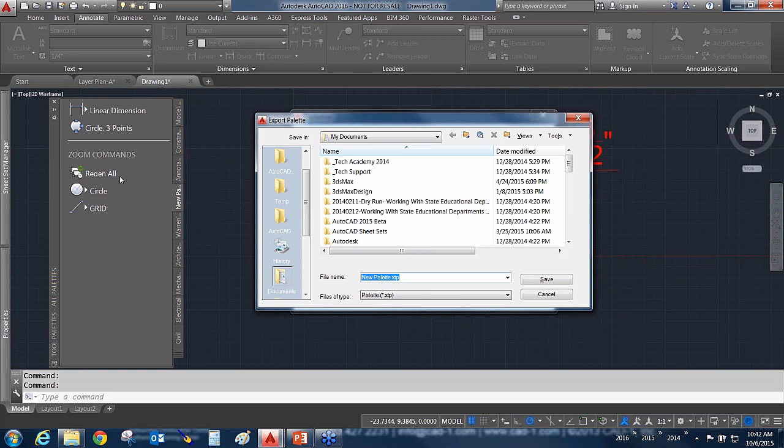So before you drag and drop a block, you've got to make sure that what we call the library file, where that block is coming from, is sitting up on a shared server, shared resource somewhere. Then you drag and drop it so that it's going to hold that particular location. Then you can go ahead and share your tool palettes all day long. Now, everything outside of blocks is pretty much irrelevant, because everything that the program's going to need is stored inside this exported tool palette. So that's what the XTP stands for, folks, exported tool palette, by the way.